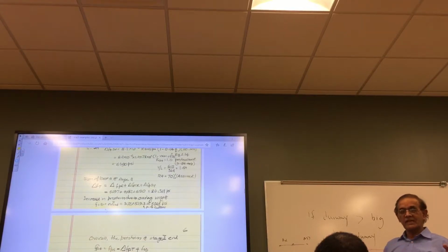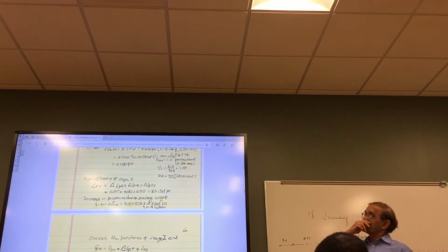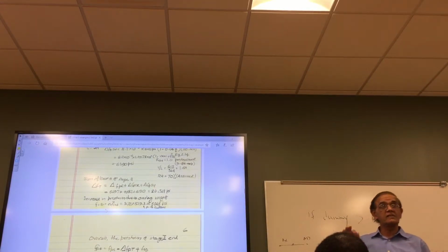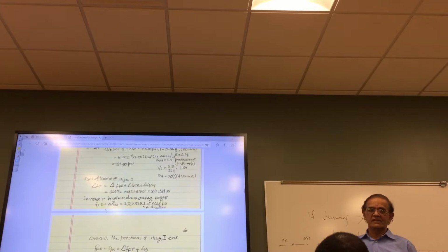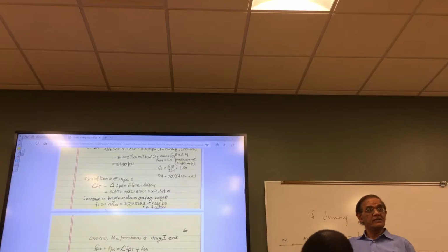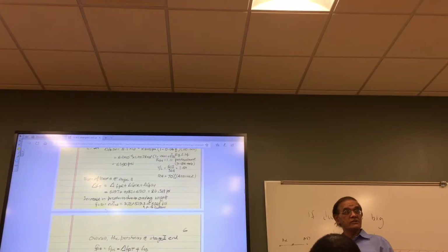But as you are stretching, you're losing the compression. In fact, there is a thing, I forget the exact word, that will come here in chapter 4, where you make the stress at the center in concrete zero. In other words, it's not tension, it's not compression. It is a neutral point. If you put further load, then the concrete is going to get into tension. But we have allowable values, 12 times square root of f'c maybe, depending on what it is. You allow that much, but if you keep doing it, eventually the concrete is going to crack.